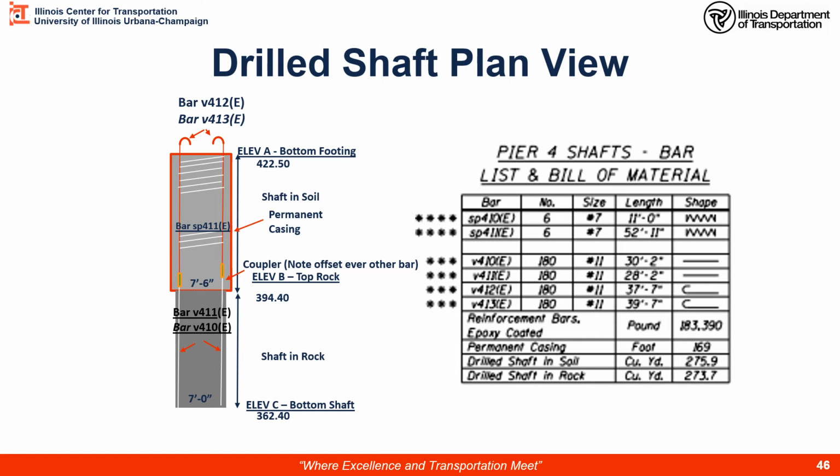Associated with the design is a bill of materials, various rebar, and cubic yards of concrete. So these will need to be checked and then measured against the bill of materials in the field.